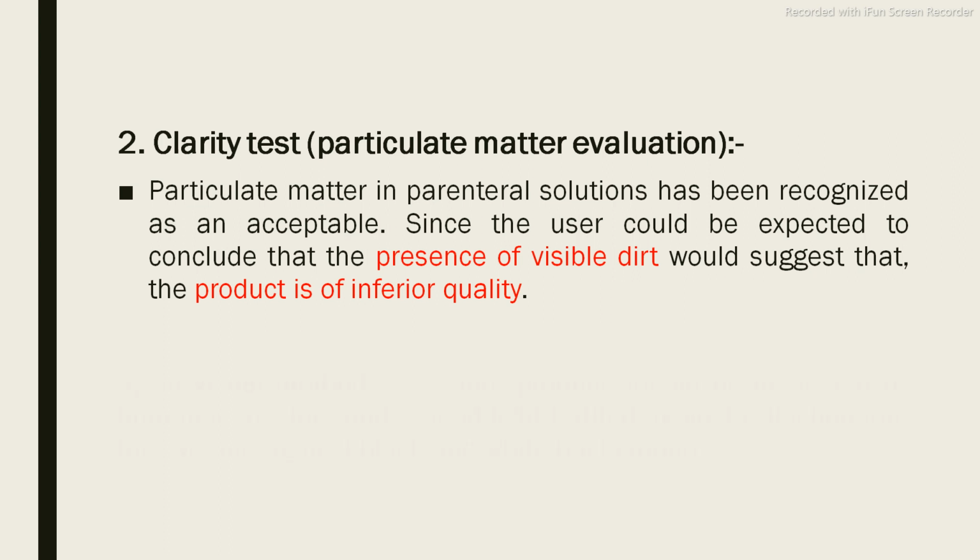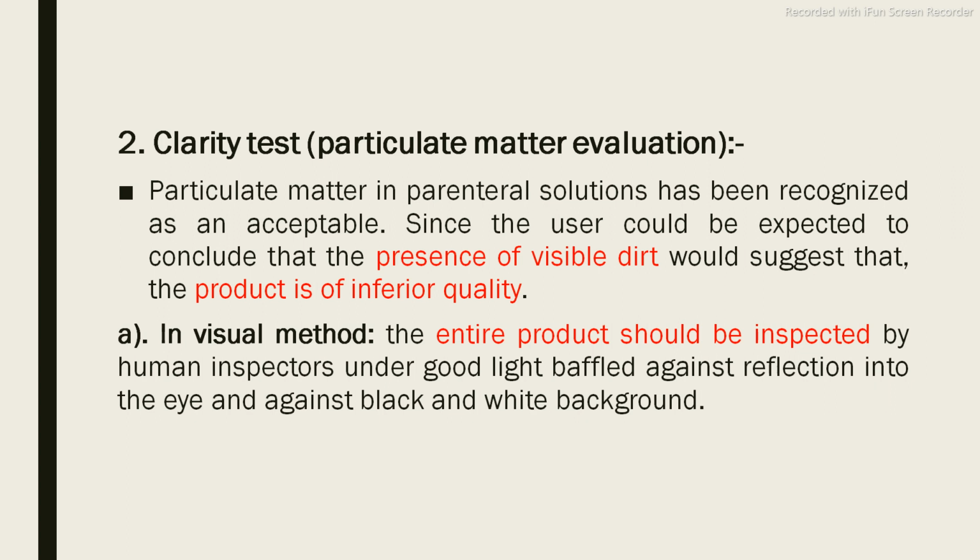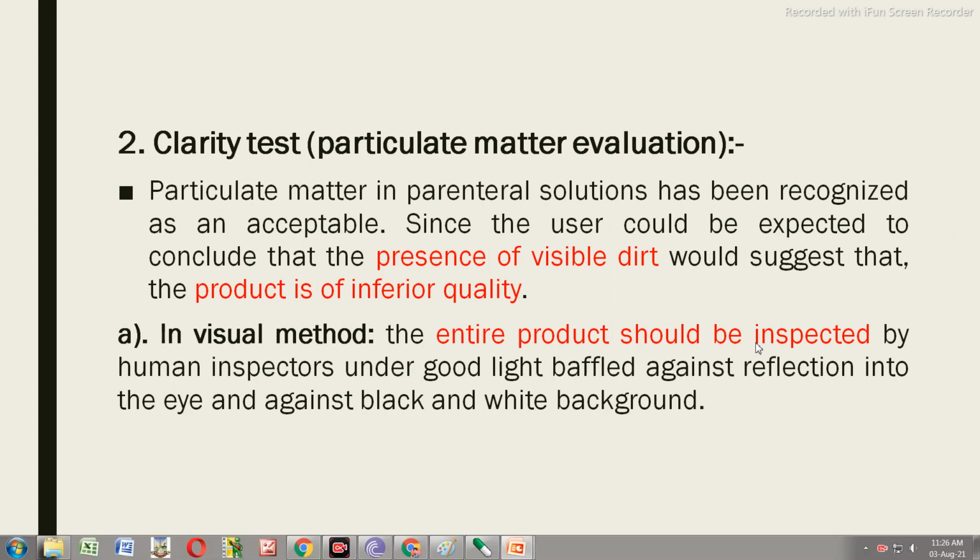And how to detect the presence of visible particles? The entire product should be visually inspected by a human inspector under good light, against reflection into the eye, and against a black and white background. This type of parenteral product is inspected by the inspector in the industries, and he can visually observe the product against a black and white background.